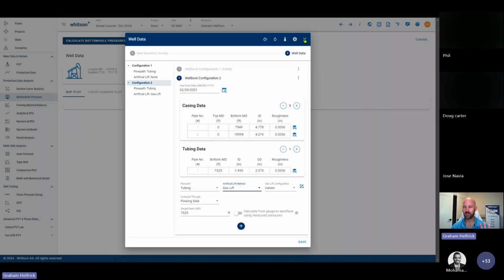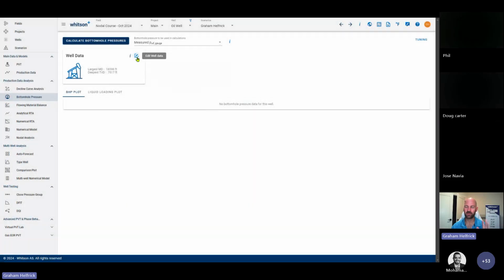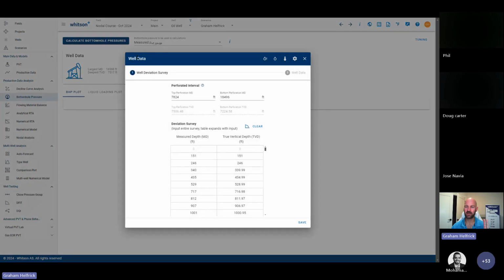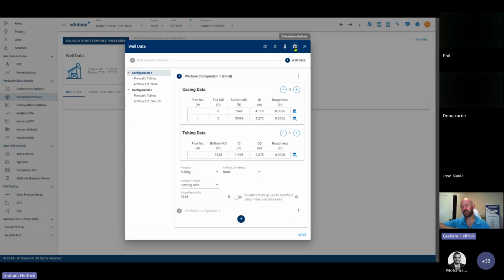Sorry, before we do that, and if you closed out, let's go back in there. There's one little option we need to toggle on. Okay, so back in to our well data card. So there was a shut-in for this well, right? And we saw that the tubing pressure built up. What we want to do is we're going to be converting that surface buildup to a downhole buildup.